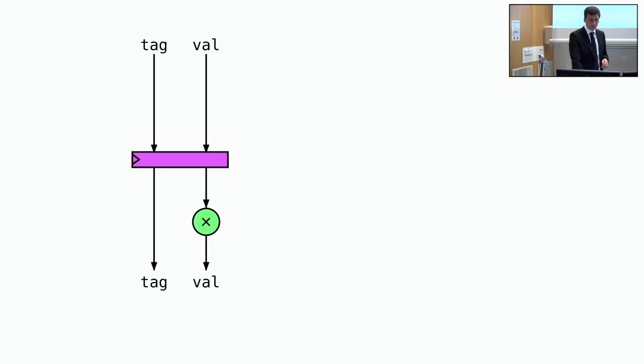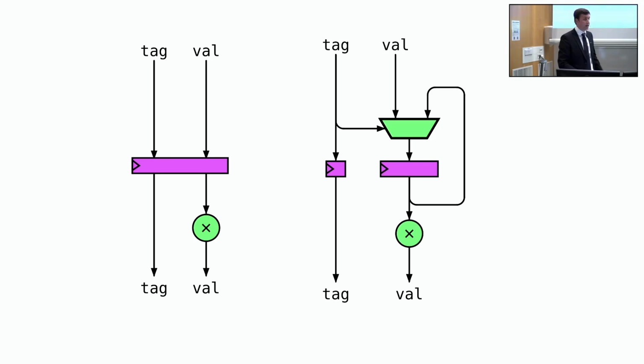In principle, the way it works is instead of having hardware like this, where we just feed the data through the computation after a register, we can transform this into feeding the tag through as normal, but instead of feeding an invalid value through, we feed the previous value back into the register. And that way, this multiplier will only have to switch values on valid data.